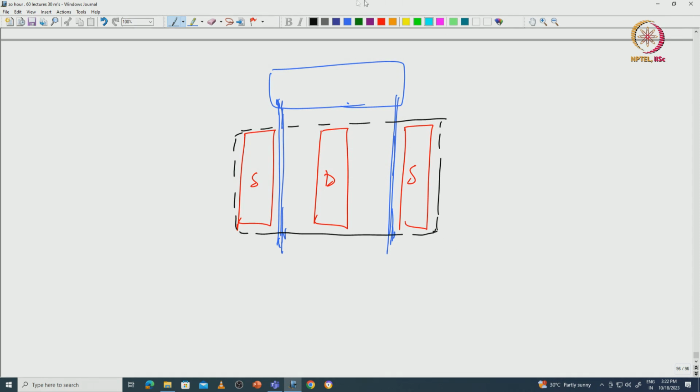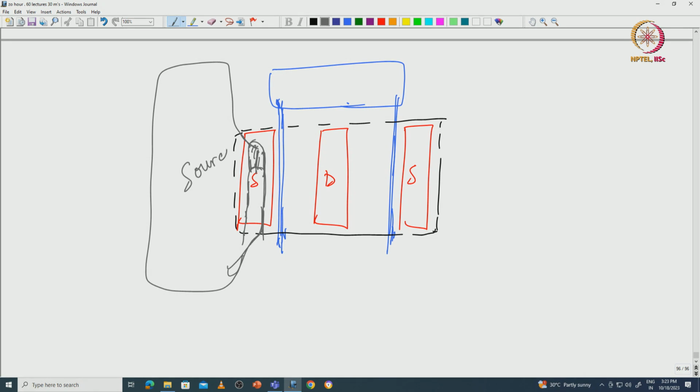Now, you do the silicon nitride everywhere, by the way, field plate, source field plate, drain field plate, passivation, etc., everything is there. So, you have to etch the silicon nitride selectively from this region. You etch the silicon nitride, so you expose the source metal below, metallically short, and you put another metal coming up here, you open this for instance, and the metal could pad up like that. So, essentially this is your source CPW pad.